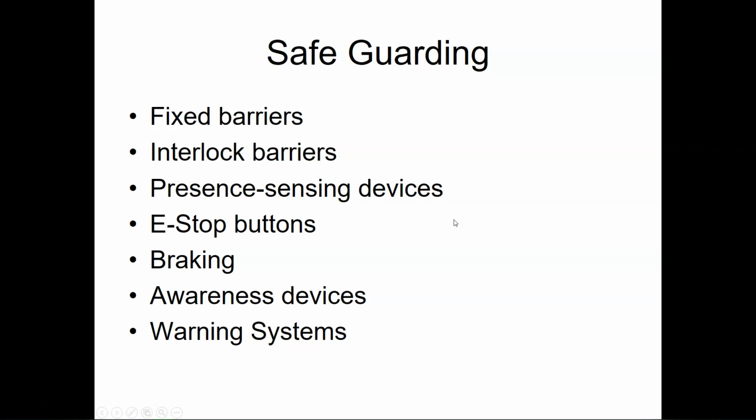You might have pressure sensing devices if the robot's out on the floor. If the robot is on the floor by itself, it might just have pressure sensing devices around it. In which case you really need to be careful, because you can very easily set those off and it may or may not make the robot turn on, and you could end up being sent flying, or it'll make the robot stop right in the middle of what it's doing. We won't even talk about how dangerous that could be to both the material it's working on, its area in the work cell, and everything like that.